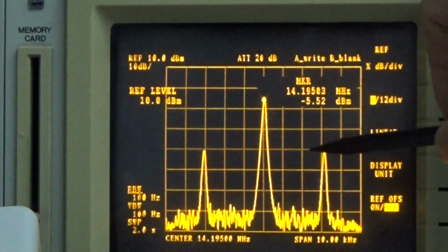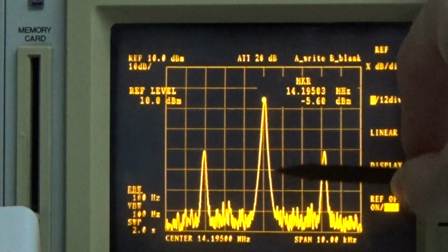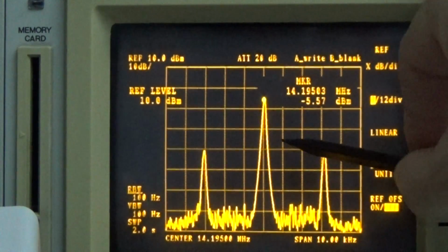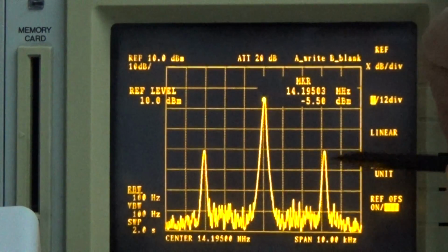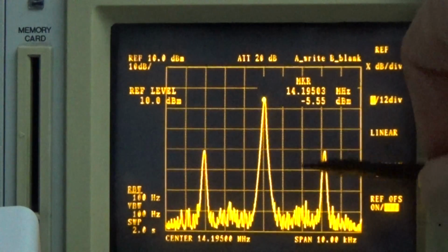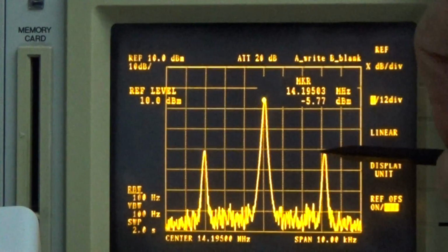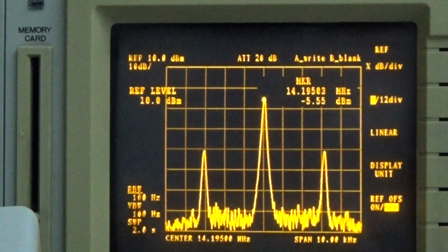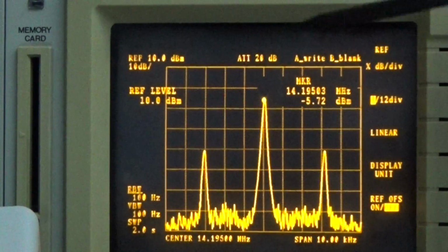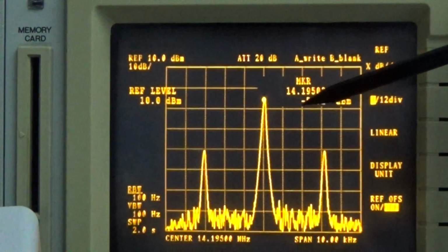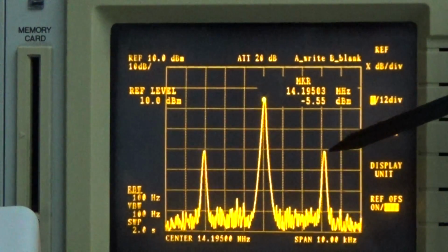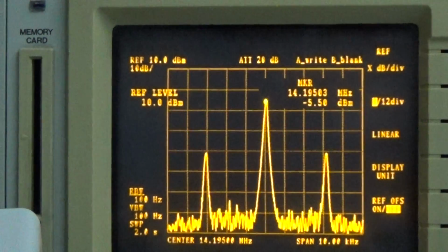If we only transmit one sideband, then we have only, like in this example, 3 kilohertz which needs to be transmitted, and not 6 as it is here in our example. And that was the basic starting point to develop single-sideband.